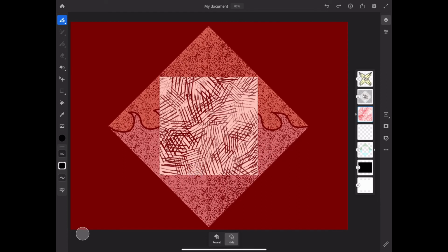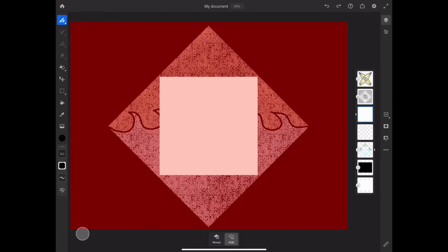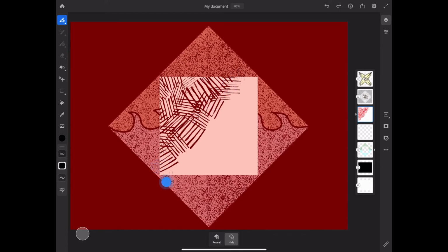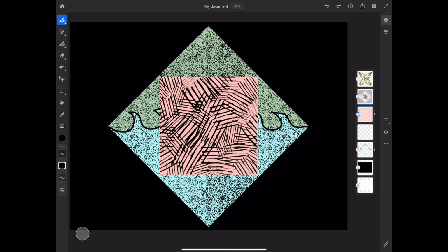with that crosshatch. And notice that it is a little grainy. And so you may have some clogged holes. So you might want to increase your pressure. You see what I mean? And it's also changing the size with how much pressure I use, which I thought was kind of cool. Okay, so that is our crosshatch mask.